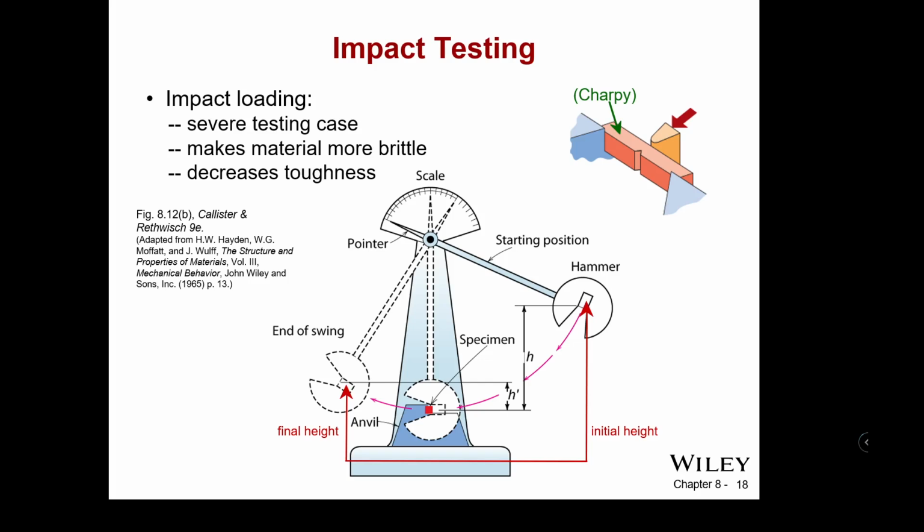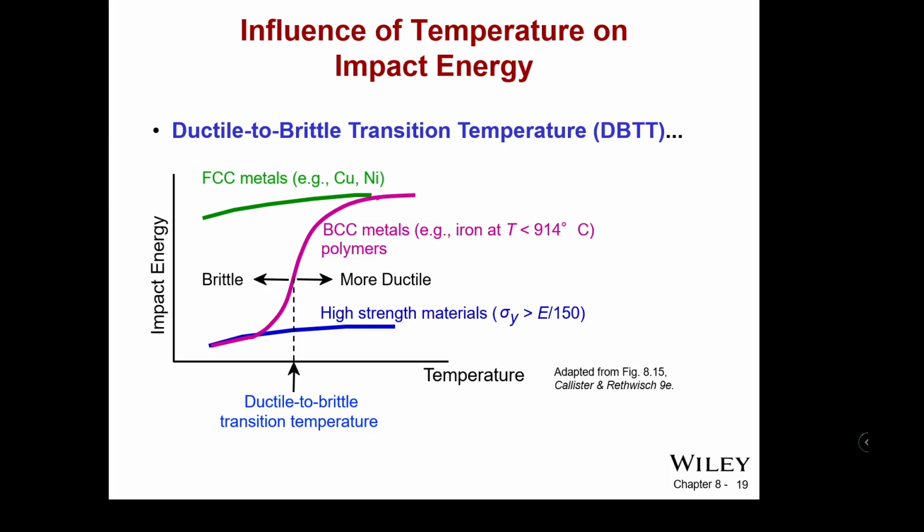That was one of the first things done with the samples there at GCU, is some much too large samples were put into place and dented and bent some things that shouldn't have been dented or bent. So it happens. The impact loading is then proportional to the difference between those. Now, our particular style Charpy tester doesn't give you that. It gives you an energy reading after the fact, but it at least allows us to better quantify and compare the results together. So it'll help to kind of see this and experience this, but that impact energy is a thing to pay careful attention to.